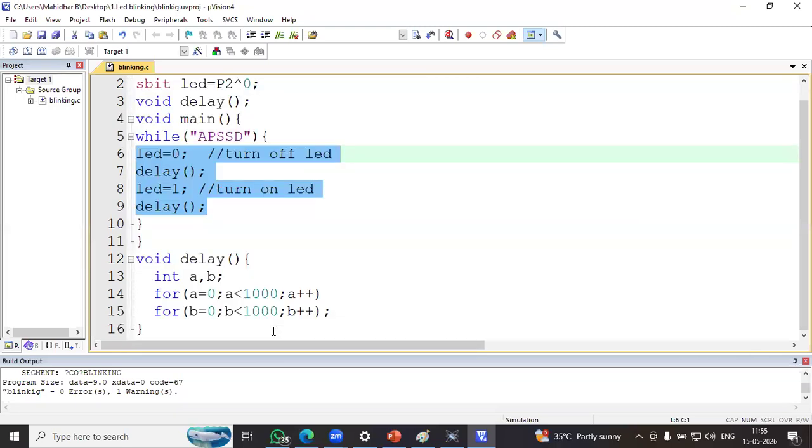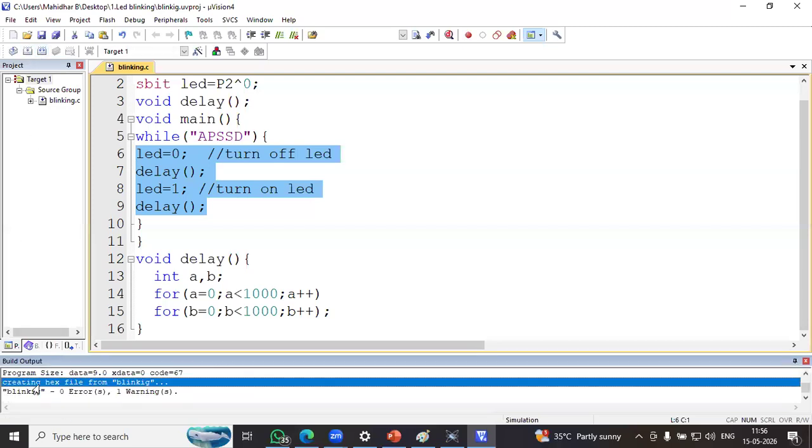Next one is to generate the file. So to generate the file, rebuild your project. After any modification, don't forget to rebuild your project to update the modifications, right? So rebuild your project. The hex file creation is done, the Keil work is completed.